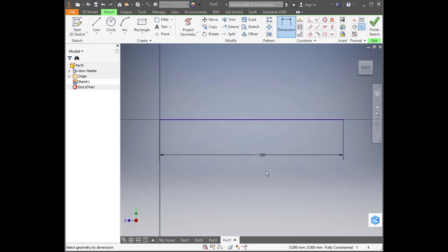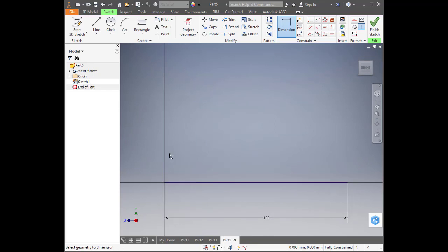Now, you're probably wondering why I've drawn a line. If I'm talking about doing my initials, which will be M and T, why have I drawn that line? I'm actually going to use that as a guideline, because in virtual space, in 3D modeling, you could be working at 100 kilometers, or you could be working at 100 microns. The computer doesn't really care. So this means that I know that that is a 10 centimeter or 100 millimeter space.